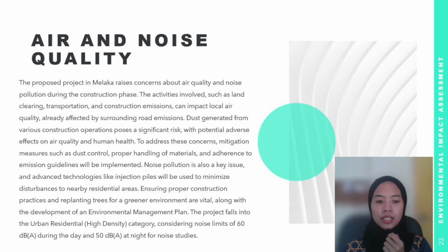Ensuring proper construction practices and replanting trees for a greener environment are vital, along with the development of an environmental management plan. The project falls into the urban residential high-density category, considering noise limits of 60 dBA during the day and 50 dBA at night for noise studies.